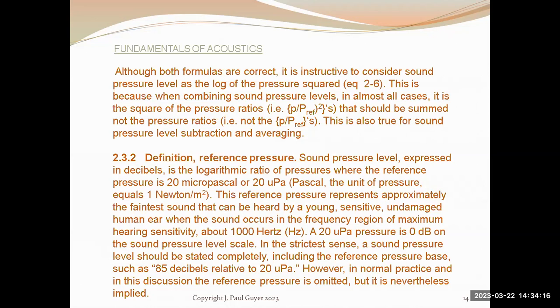And in the strictest sense, a sound pressure level would be stated completely as, for example, 85 decibels relative to 20 micropascals. But we don't bother doing that because the 20 micropascal reference pressure is so well known and recognized.